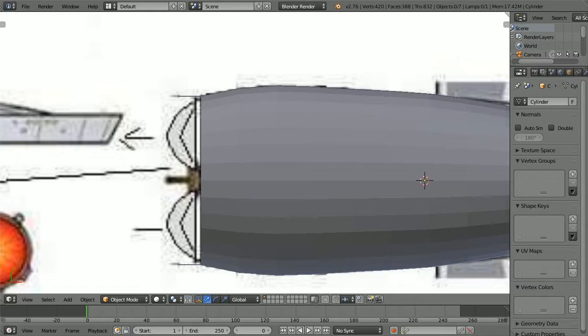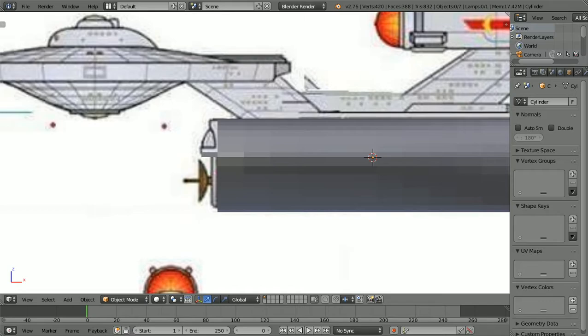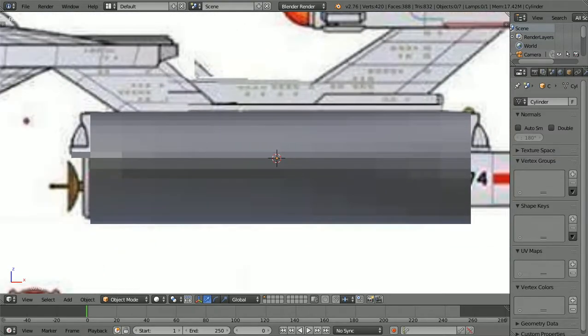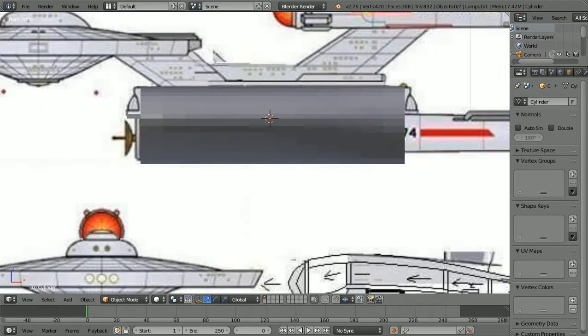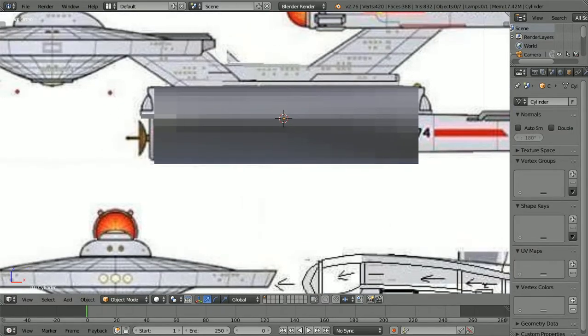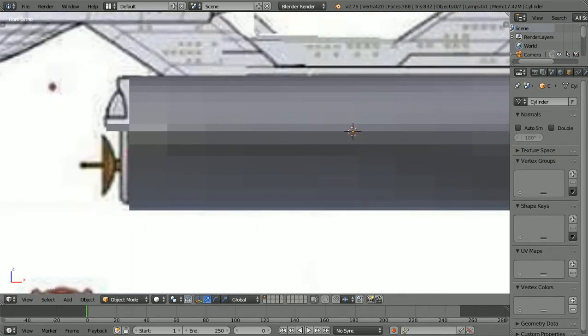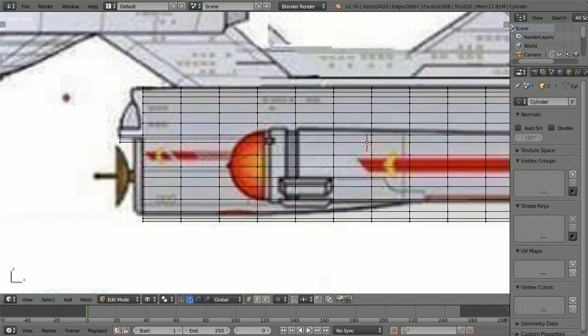So now, what I want to do is, I was actually wanting to shape the bottom of this hull is what I was kind of wanting to do. So to shape the bottom of the hull, we need to, actually, okay, what I want to do, I'll grab this as an object. We'll go into Edit Mode. We'll push Z. Okay. Now I got two options here.